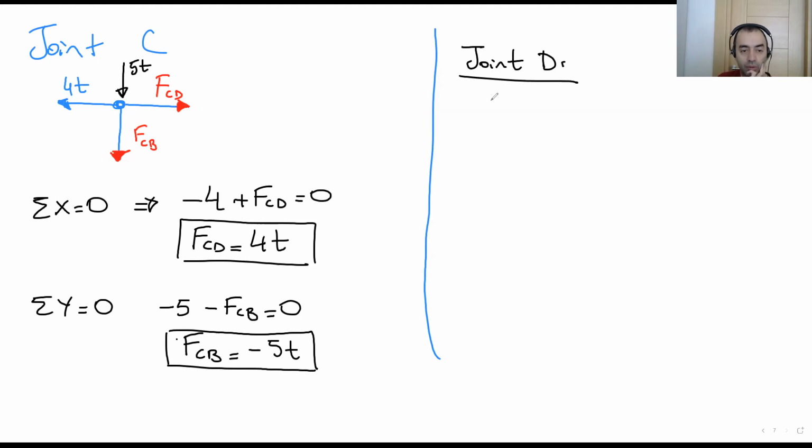It looks really complicated, but if you do some practice by yourself, you're going to see this is really easy. You are not doing anything more. You take the joints one by one out and write the equilibrium equation. The equilibrium equation means here total X and total Y is 0. That's it. It's not a moment equation.